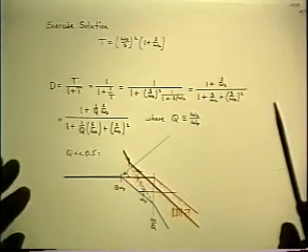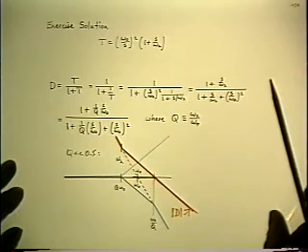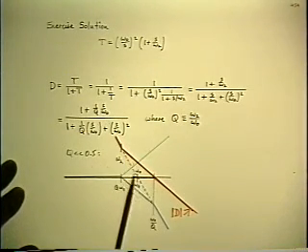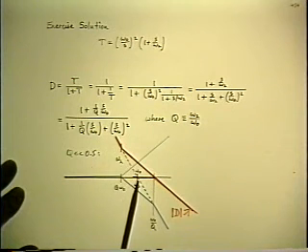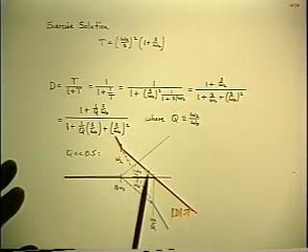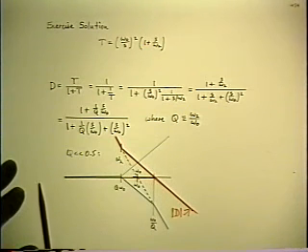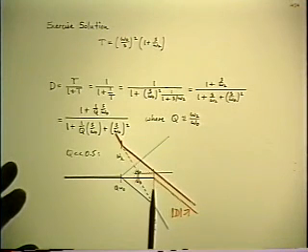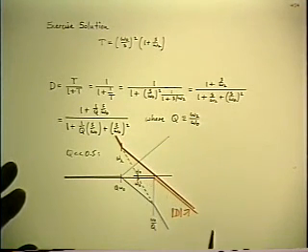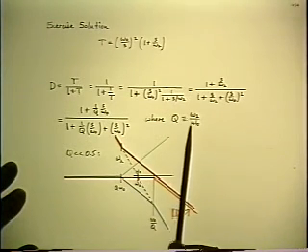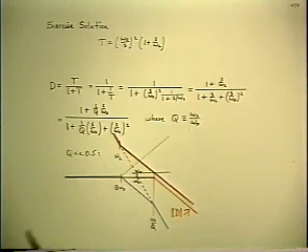If I superimpose that on top of the original picture of the loop gain, this is the loop gain coming down to extrapolated crossover at omega 0, and this is the position of the compensating 0. And the closed loop gain simply stays flat until the single slope crosses over, and then the closed loop gain follows the T. In other words, as long as Q is low enough to justify the real roots,